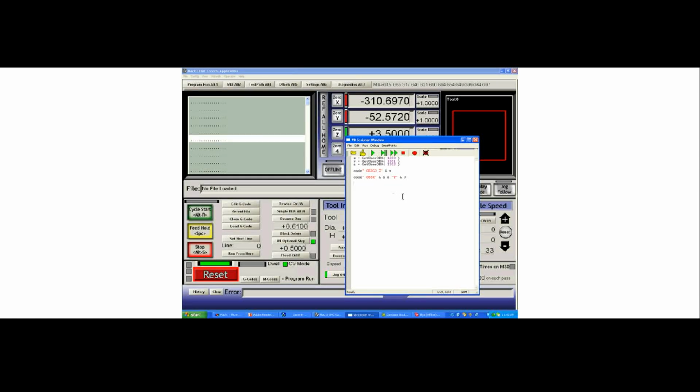Let's say at that point we've moved our tool back to a machine coordinate of where we wish to change our tools. We could do other jobs such as zero those controls. So we can type set DRO 0, 0. This is a Mach3 command which will set the X DRO to whatever number you put in, and it does that by changing the fixture offset coordinates, or it's the same as pushing the 0 button. We can then say set DRO